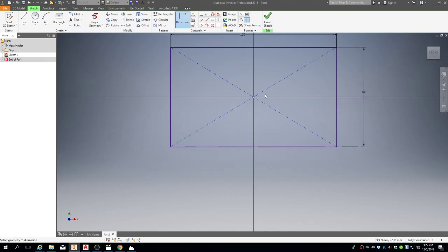Right. The lines you see here are purple, and that's because purple is perfect. If you've got green lines, that's okay. But for this project, purple means perfect, and that means that they're fully constrained. The dashed lines you see going across the corners, the way they're connected in the corners, the dimensions all add to the way that this thing's been constrained.